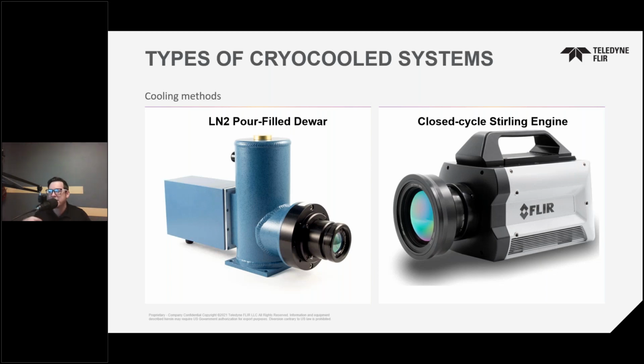So we can set the integration time to tell the pixels how long to remain open to collecting that photocurrent into that capacitor. If we fill it to the top, we get a saturated pixel. If we fill all the pixels, then we get a saturated image. Too little energy captured, and we get a grainy image. Therefore, a good proxy for integration time is exposure time in the visible light camera world.